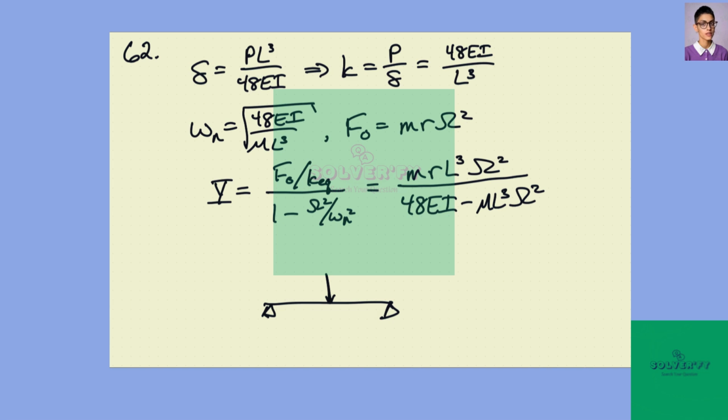So anyway, that's what this is. And again, given the shape of the cross-section of this beam, you could figure out what that is, and given the material that the beam is made out of, you can get that. So we want this spring constant. That's P, the force, divided by the deflection at the middle. And so we can just multiply through by this, and we get that the spring constant is 48 EI over L cubed.